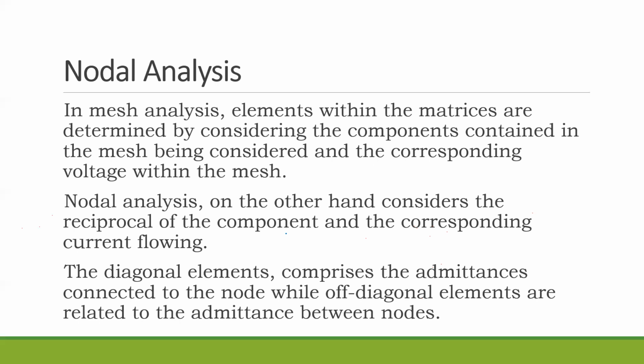In mesh analysis, for the diagonal elements, we look at the sum of the elements within a mesh. For nodal analysis, we look at the sum of the reciprocals of the elements connected to the node. In other words, if you know mesh analysis, you automatically will know nodal analysis. To be fair though, it is not as simple, but doable. So let us see how we do that.